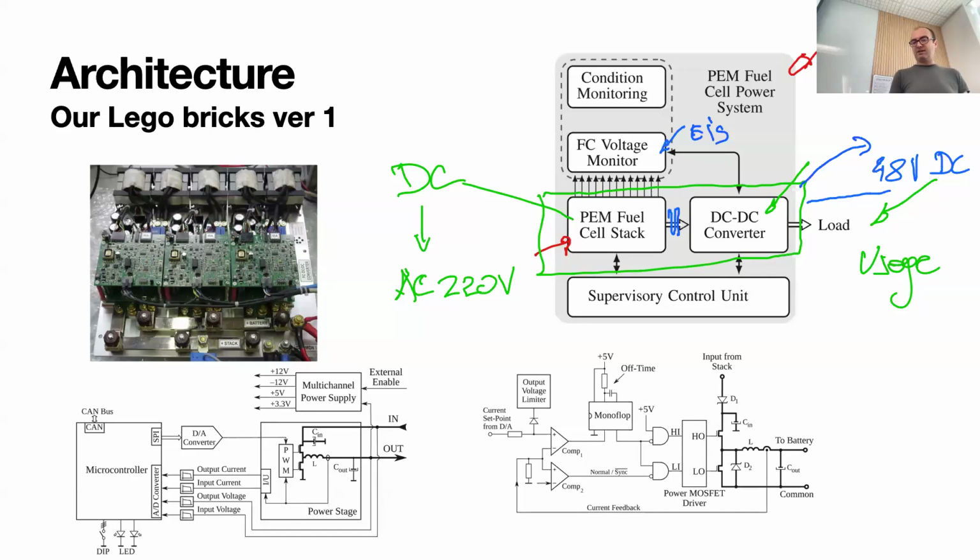So the fuel cell was operating, and every X hours or X days, whatever was decided, we were able to excite the fuel cell within this internal loop, make a data acquisition with the voltage monitor that I'm going to talk about, and calculate ICE and do any further analysis that was then conveyed to some supervision unit or a real-time optimization unit or mitigation strategies or whatever.